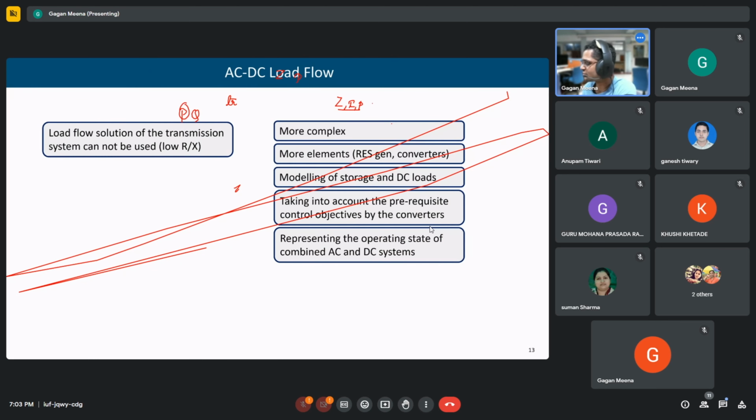Impedance, current, and power. Each of them will have a particular weight, and the sum of those weights will be 1, depending upon which of these is given more weight. And then there are exponential load models also. So different types of models are there based upon the different equipment that we use at our homes: refrigerators, air conditioners. Detailed studies have been conducted to find out the type of model for each of these equipments.